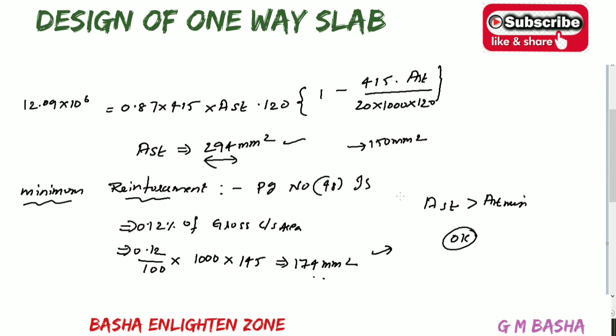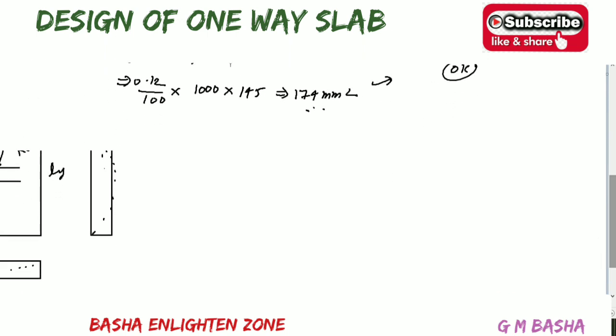Here if your area of the steel is less than that required, then at that time you have to limit this value to this one. So you have to provide a minimum of 174 mm square area of steel in that particular slab. Whatever we are providing according to our condition, it will be higher than this one. So it is in the safe condition only. Like that you have to check according to our Indian Standards whether whatever you are doing is according to the conditions or not.